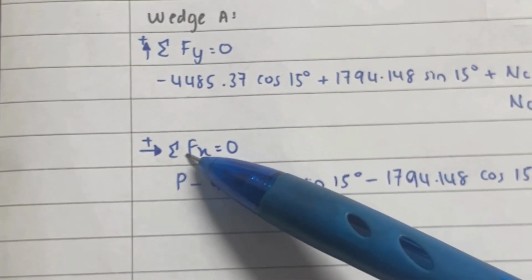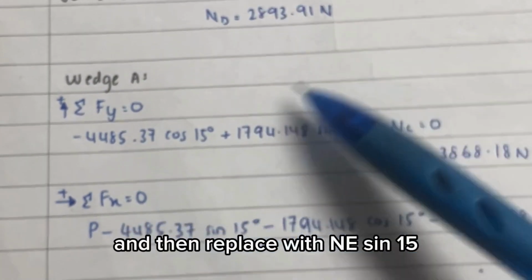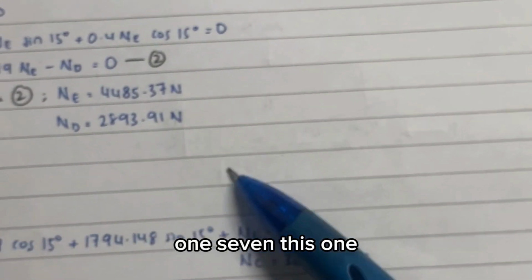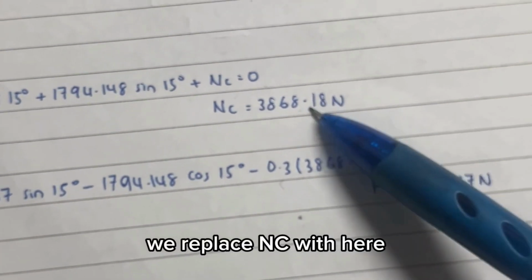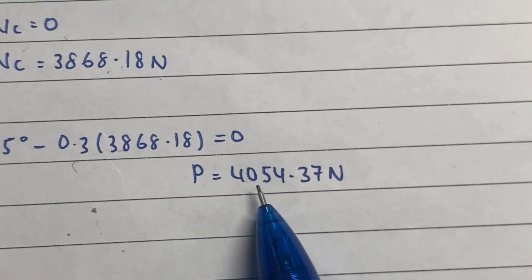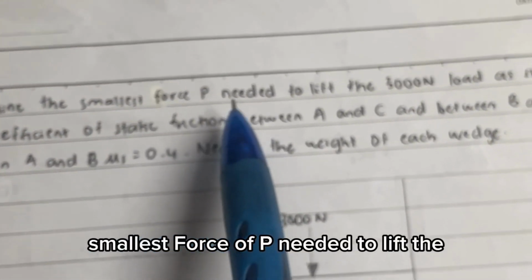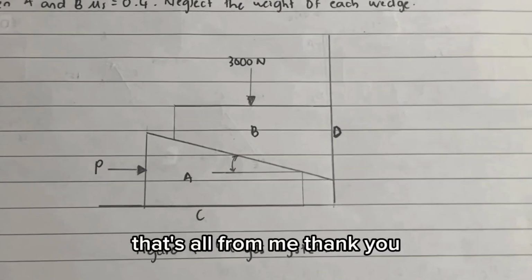For Fx equal to 0, we got P, and then replace with Ne sin 15, subtract this one, and then cos 15, we replace NC with here, and then we got P equal to 454.37 Newton. It is the smallest force P needed to lift the 3000 load, and we got the answer. That's all from me. Thank you.